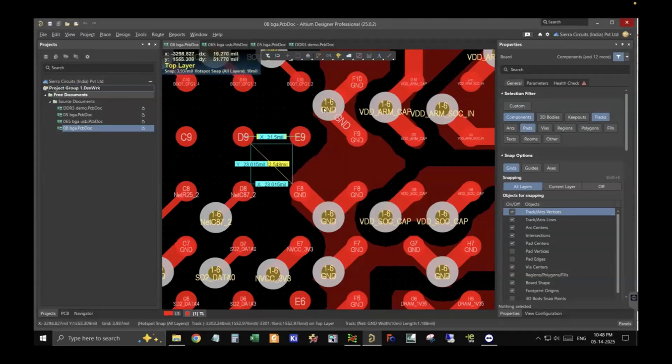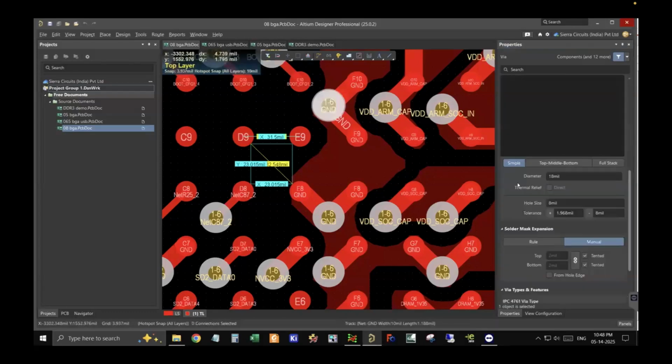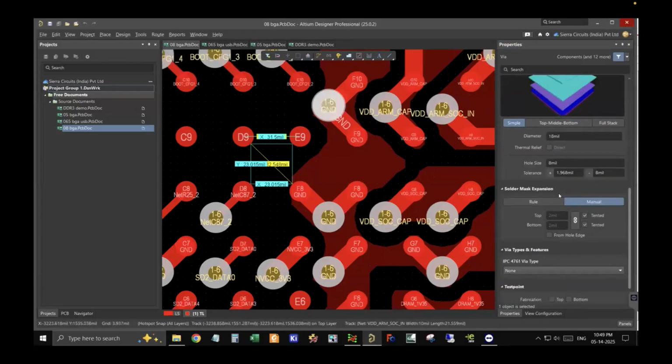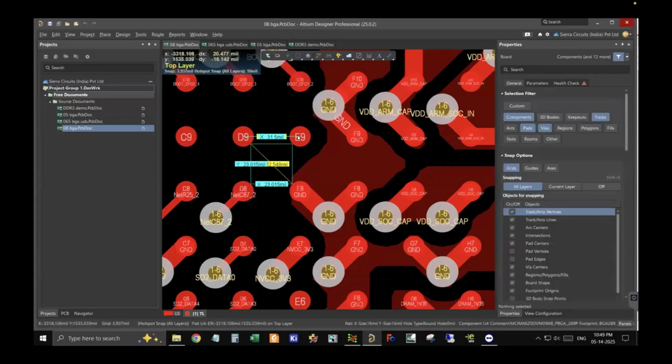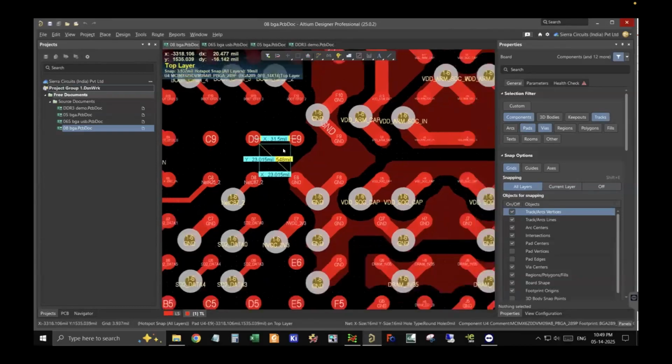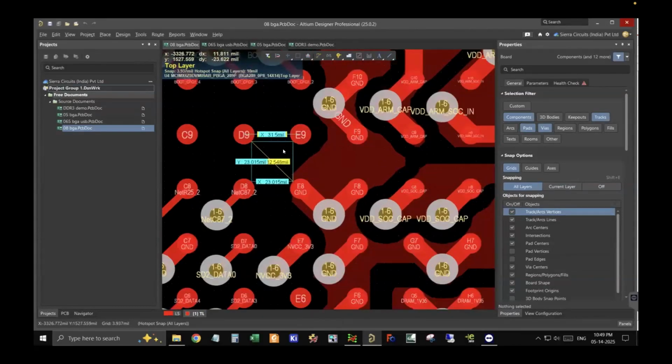So now, when it comes to wire selection, this is 0.8 and 1 also you can consider the same thing. In this case, 32 mils is available over here. So easily you can place a normal wire, which is 8-18 mils or 10-20 mils, whatever you feel like. So you'll have enough space on both ends. So that shouldn't be a problem. You don't require via in pad, or you don't even require blind and buried vias, so you can use dog bone structure. Only thing you will have to look at is the stub length of your via. If your frequency is too high, then you might have to go for back drilling, or you might have to use the blind and buried vias just to avoid that stub length.